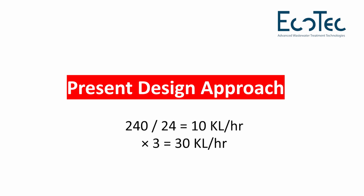Now, let's take the present approach towards how peak factor is considered. Let's say we've already assumed that it's a 240 KLD plant. Divide by 24 gives 10 kiloliters per hour. Now, when we put a peak factor of 3, the total volume comes to 30,000 liters per hour. This is the usual approach from designers.